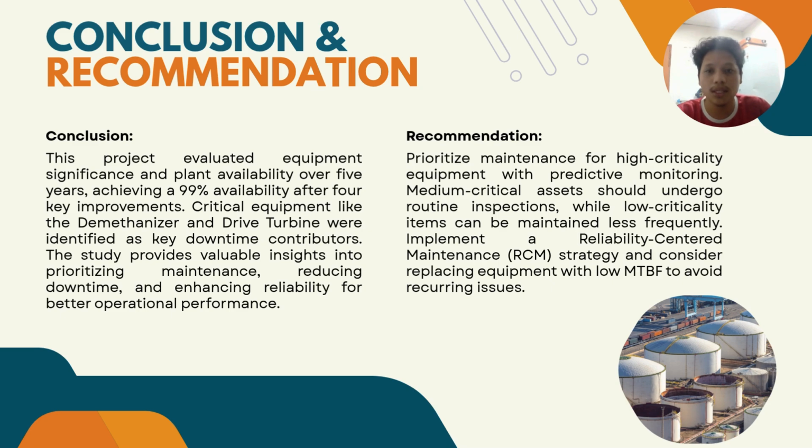To conclude, this project evaluated the plant's availability over 5 years, achieving a 99% availability rate after implementing 4 key improvements. We identified critical equipment like the demethanizer and drive turbine as major contributors to downtime. By focusing on these, we minimized system failures and boosted operational performance.